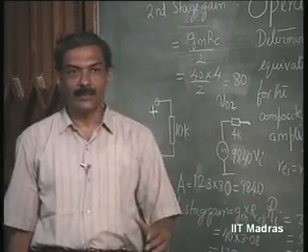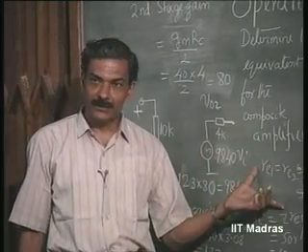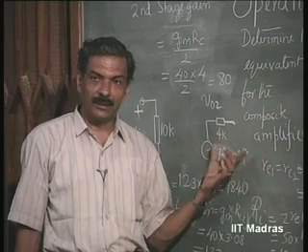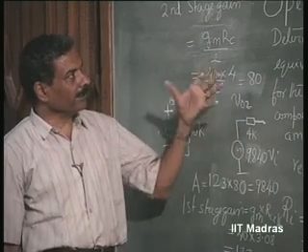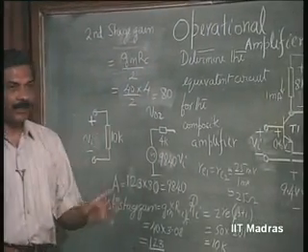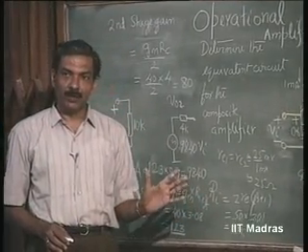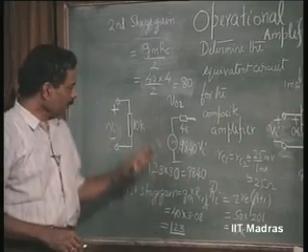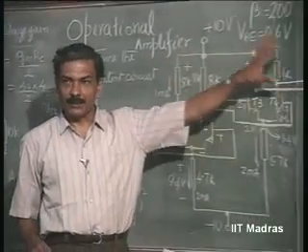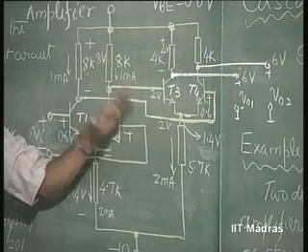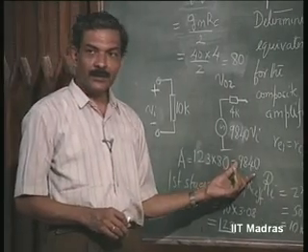just as we had in the beginning of this course defined basic control sources as voltage amplifiers, current amplifiers, transresistance amplifiers and transconductance amplifiers. So, the main fact in designing such operational amplifiers is making sure that the amplifiers are cascaded and the transfer parameter is as high as possible. And then most of the analysis could be carried out by using this equivalent circuit instead of this complex circuit. Now, as far as this is concerned, let us once again see the gain being of the order of 10,000 or so.